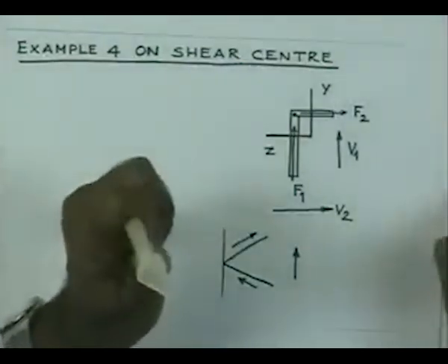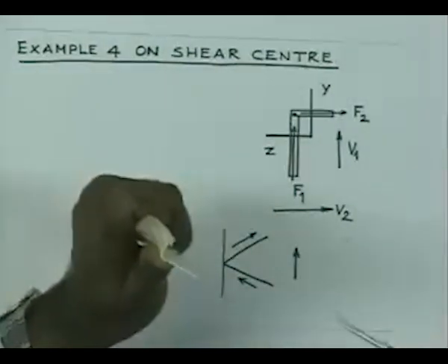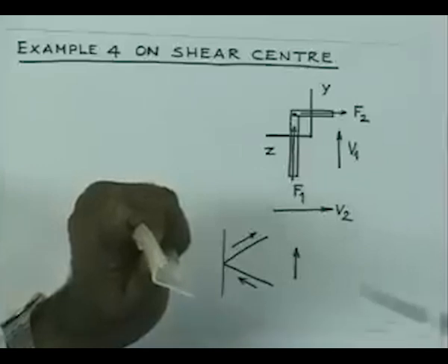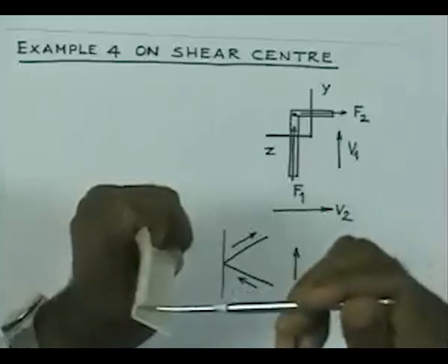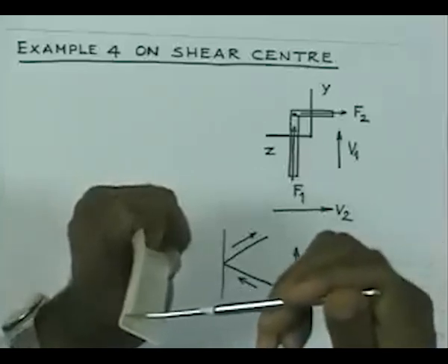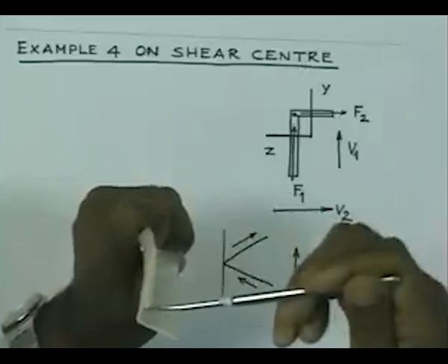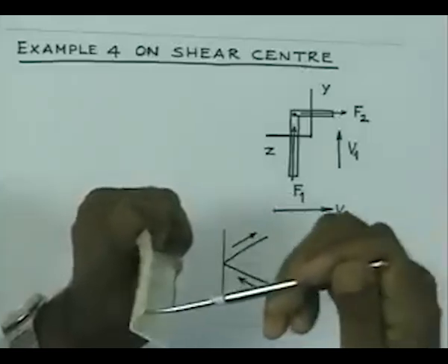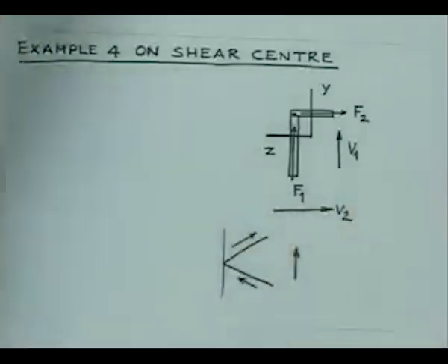See that this is the section, now we are trying to keep it at an angle. So, I am keeping it at an angle, and therefore, now if I put the load passing through this point, it does not get twisted, its orientation remains. So, you can consider solving examples by considering problems which are given in L.S. Srinath, Advanced Strength of Material.